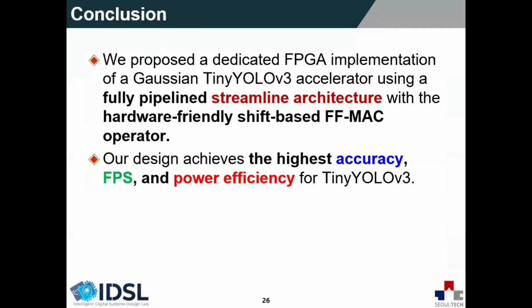Let me conclude our design. We proposed a dedicated FPGA implementation of a Gaussian TinyYOLOv3 accelerator using a fully pipelined, streamlined architecture with a hardware-friendly shift-based FF-MAC operator. Also, our design achieves the highest accuracy, FPS, and power efficiency for TinyYOLOv3.